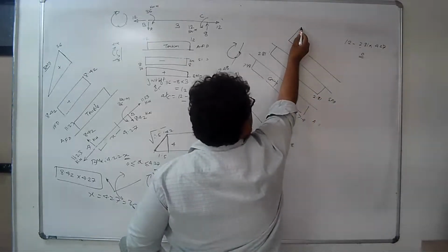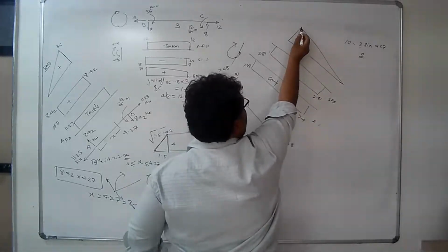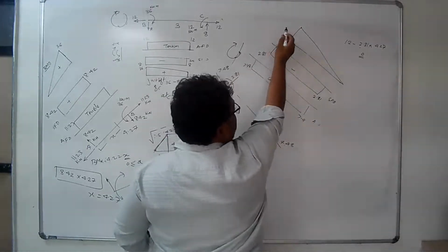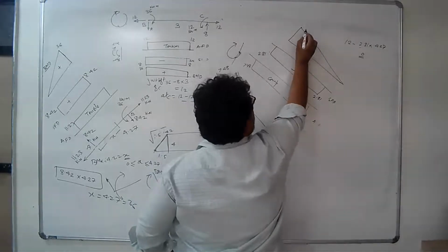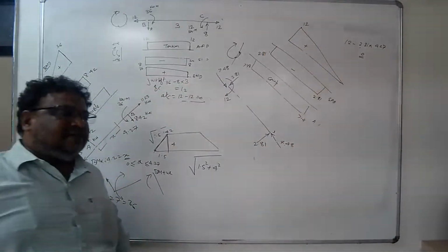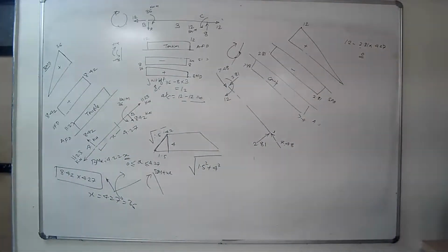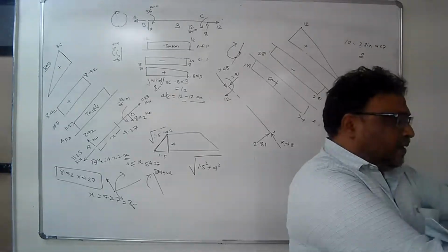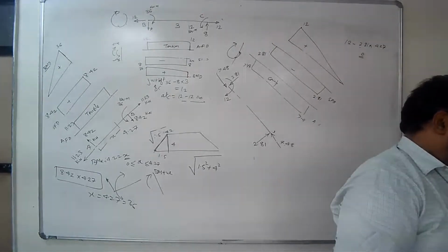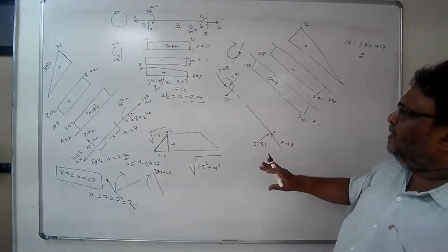So यहाँ से and the bending moment variation is linear, क्योंकि बीच में कोई UDL और कोई दूसरा लोड नहीं है, यहाँ कपल है, and because of this concentrated load the variation will be linear. So this is positive and this will be 12. Is it right? Is it okay? Yes, it is right. ठीक है, ये समझ में आया है क्या? Is it all right? This is how we can sketch.